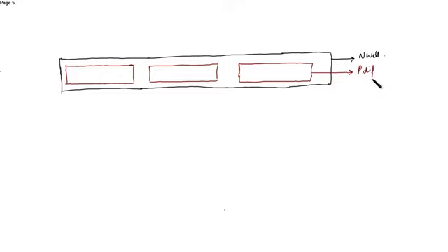This is the P diffusion layer. So now this whole is our PMOS. Now after drawing the P diffusion layer, next you have to draw the N diffusion layer, most equal in area with the P diffusion.